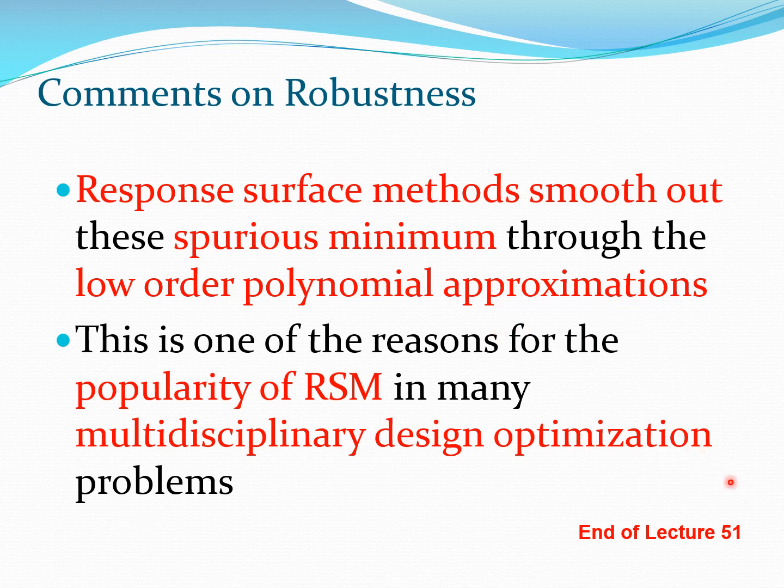So again, this is one more reason for the popularity of response surface method in many multidisciplinary design optimization problems. Like I told before, such problems would involve solving a lot of partial differential equations in the fluid and structural domain, and you would have nonlinearity present also. So you may have situations where different people, different groups, different codes do not converge to the same level, and a lot of these aspects can be mitigated by using response surface methods.